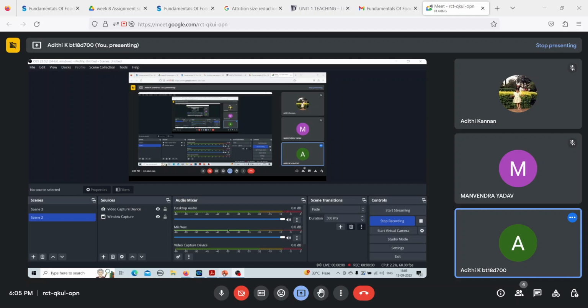So you have sieves arranged one on top of the other, and on the top you will add your food particle and you will keep shaking it. So all the particles that are of smaller size than 100 micrometer, let's say 100, will go down to the next. Particles that are smaller than 50 will go down to the next, then the next, then it will reach the final collection pan where we collect the particles. And particles that are larger than this particular size will be retained in these sieves.